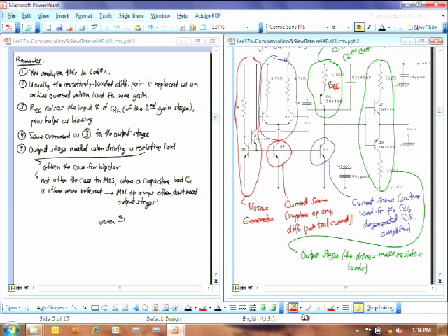Plus it helps with biasing in the end. So it's easier to bias this up if it has this resistor there, because you want a certain voltage coming off of this here. If you didn't have that resistor there, you'd have to drop 0.7 volts across this resistor here. But now that you put that resistor there, you can drop anything you want there, and you can make this output whatever you want. So there's multiple reasons why that resistor is actually there.